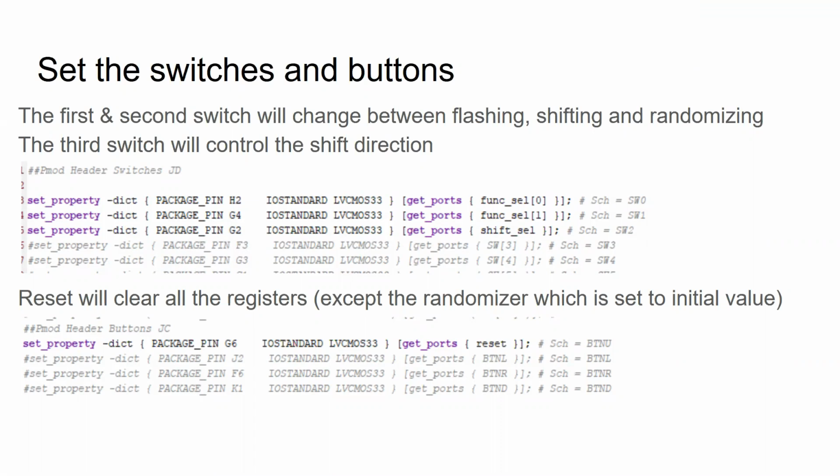I'm not sure if you talked about this already, but do we have to do anything with the time scale that gets automatically generated if we create a user? Nope, it's always 1 nanosecond. Our silicon isn't good enough to be in the picosecond range, I think. Not yet. Not on FPGAs, that's for sure. Maybe later. But in the ASIC world, everything is picoseconds and femtoseconds, and it's fine. But not with FPGAs, no.